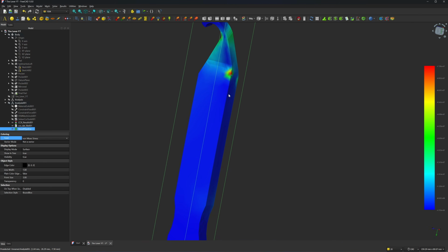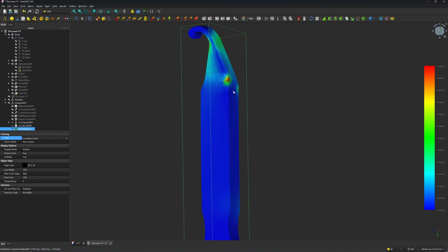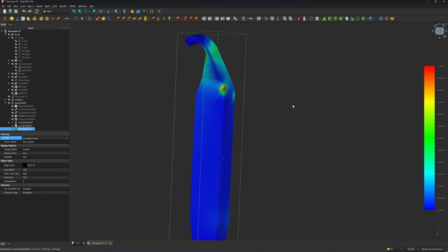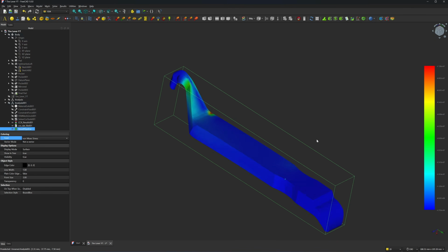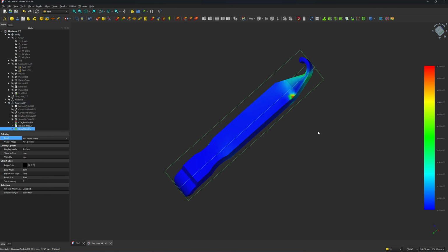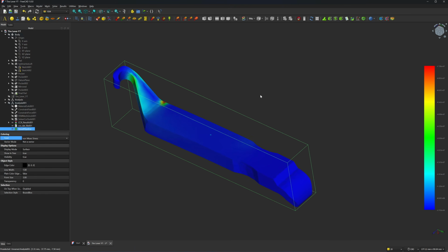It's closer to the part where you hold your hands. So when you remove the tire bit, your fingers will be here. So it will be the support. Anything above this light green color will break. So this part will break if you apply 6 kilograms of force. All right. Okay. So you can estimate and predict the behavior of your design, when it's going to break. Is it strong enough, or can you save some material with the proper thickness. Okay.